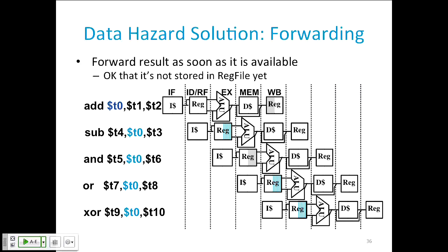right? And similarly, for this instruction, it's even easier. This just needs the value here. I know the value at this point, so I can forward it from here to this input, to this ALU. These guys don't matter. And these are the forwarding paths I'm going to add to the hardware design, right? So the key here is that I know the value, I've already computed it. It exists in the machine at that point in time, I just need to route it by adding some extra circuitry to get from where it's produced to where it's needed, right? So by doing this forwarding trick, you can execute these instructions in one of the pipeline clock cycles, even though they depend on each other.